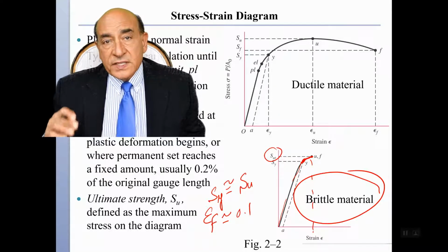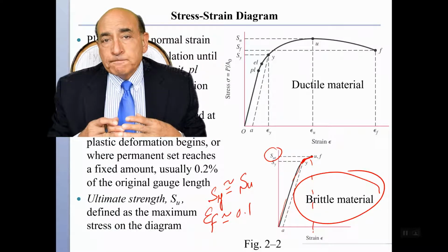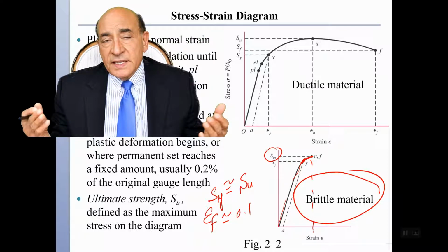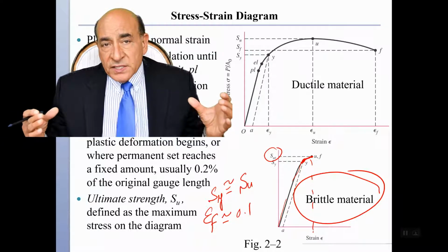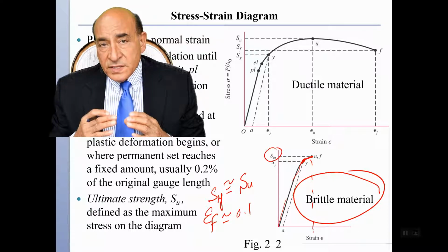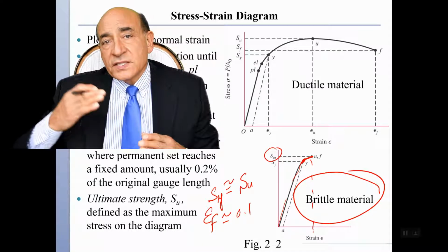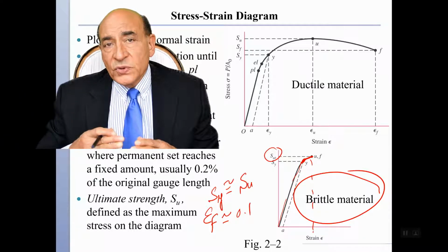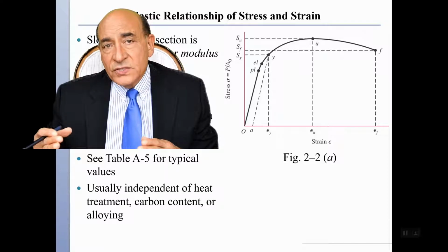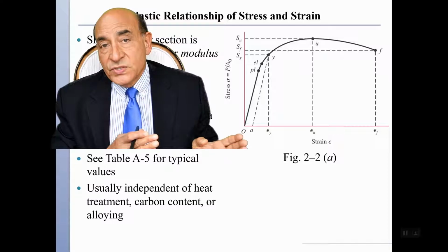So these are the general characteristics for the engineering stress strain curve, and what we require to understand is that as the material deforms, let's say that the length increased by 60%, the cross-section is going to shrink also by a great amount, and therefore if I consider the current state of the material at each loading step, its length is going to be different, its cross-section is going to be smaller, and therefore the local values or the current values of the stress and the strain would be substantially different from what we measure if we were to just use the initial state.